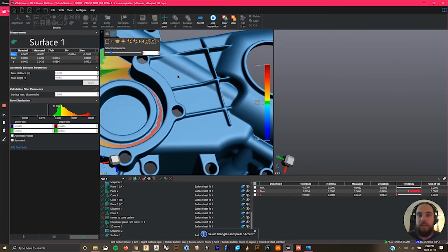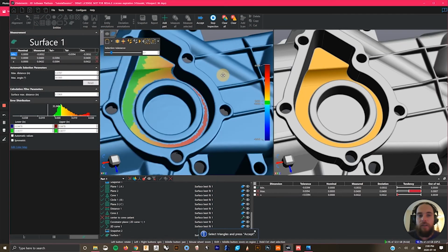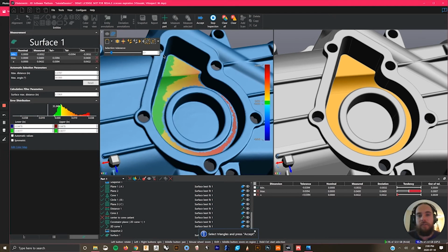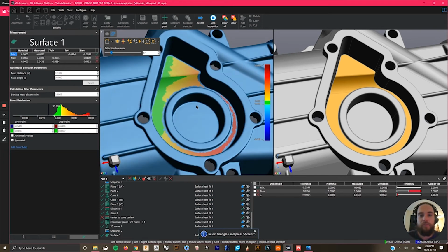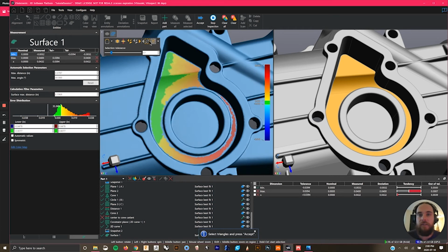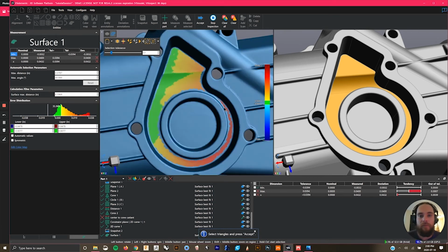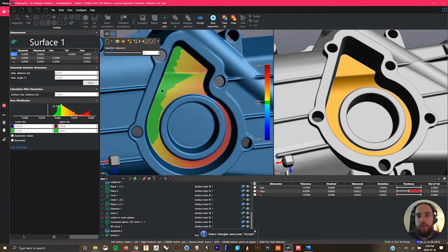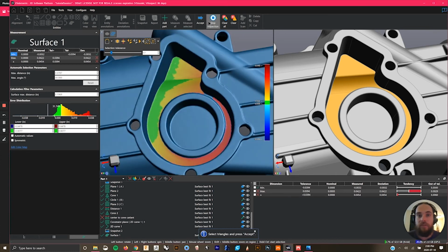Once we measure selected, we come across this double screen again, which is really cool. On the left-hand side, we have a bunch of tools to help us with our mesh selection in order to ascertain exactly which part of the mesh we're measuring. For me, all I need to use is one of the grow commands in this mesh island toolbar. If I use the grow command, you'll see that it's going to grow that selection of measurement well into those areas that I wanted, which is perfect because we get a more accurate result. And then if that's all I needed, I'm going to hit accept.